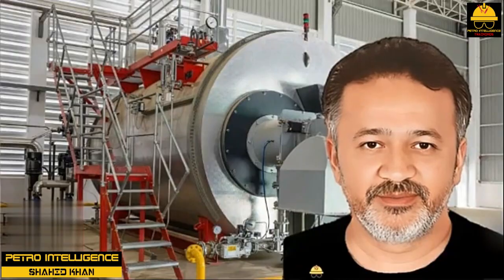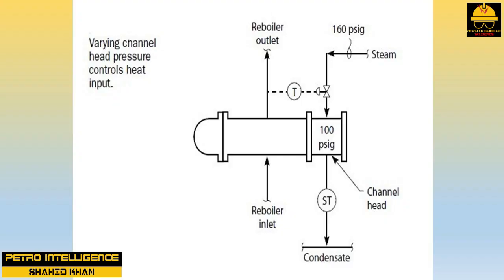Condensate control. Once the steam pressure in the channel head in this picture falls to the pressure in the condensate collection header, the steam trap can no longer pass condensate. Water will back up in the channel head and waterlog the lower tubes in the tube bundle. This will lead to unstable steam flow control. This is especially true if the steam supply pressure is less than 20 psig above the condensate collection header pressure.